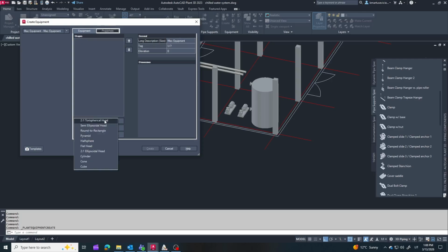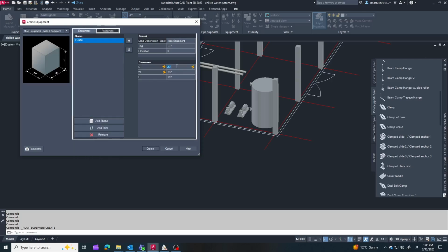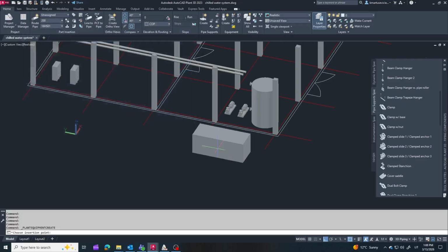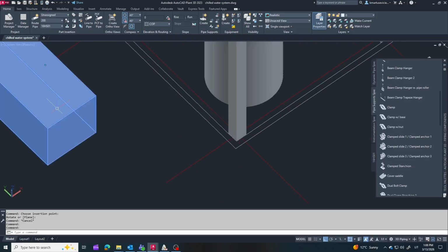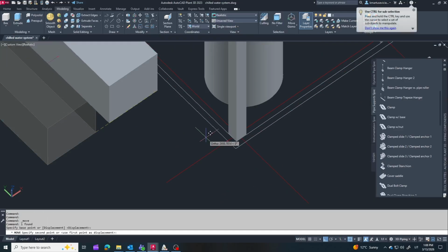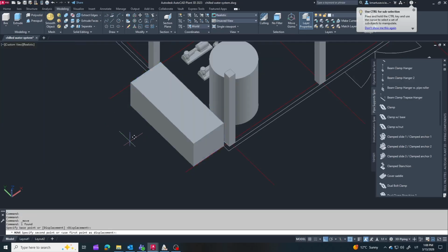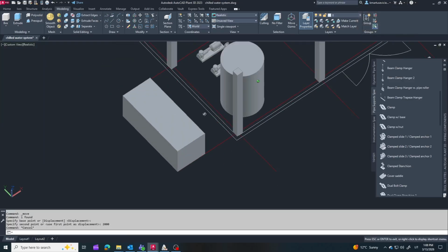Now I will create the chillers themselves. At this stage, I just use large boxes as simple placeholders. Later, I will add the nozzles and other details. I place the chillers outside the building because they need a good air supply and airflow around them for heat rejection. I leave about 2 meters of space from the building wall and from other chillers.